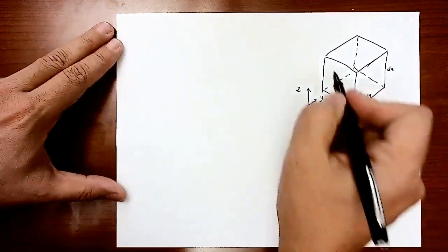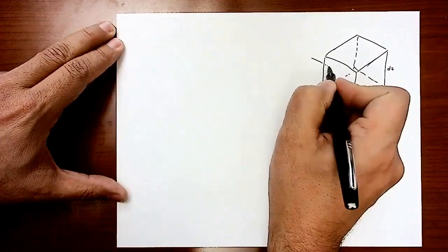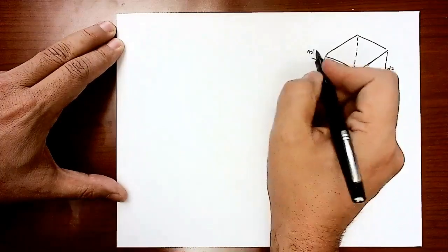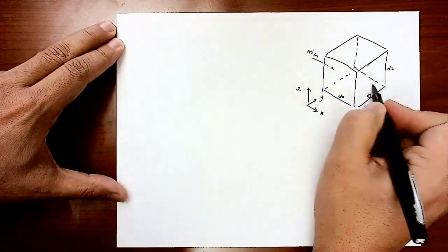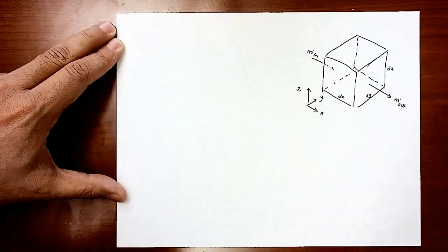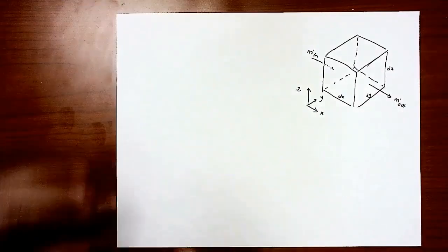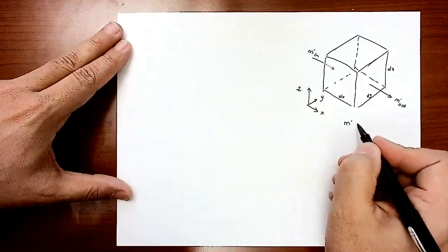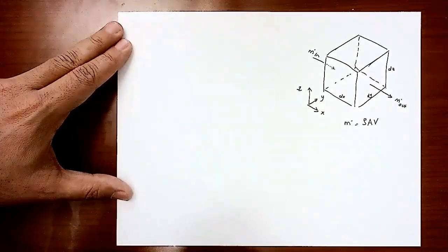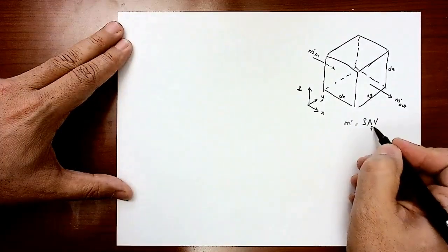So we have a mass flow rate coming through the back face of that control volume. I'm going to call that m dot in. Then I know that there is mass going to leave that face here. That's m dot out. How do we calculate the mass flow rate? Remember, mass flow rate is simply rho times A times the velocity, and A is my flow area, right?